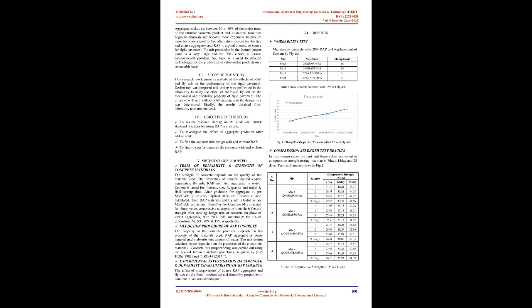According to NAPA, the current annual U.S. production of new asphalt pavement material is approximately 500 million tons per year, which incorporates about 60 million tons of reclaimed material that is reused or recycled directly into pavements. As of 2007, about 40 million tons of RAP is reused or recycled into other pavement-related applications per annum, for a total use of over 100 million tons of RAP each year.